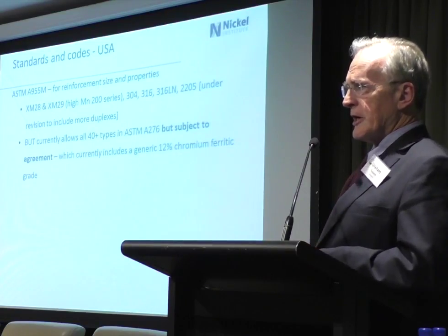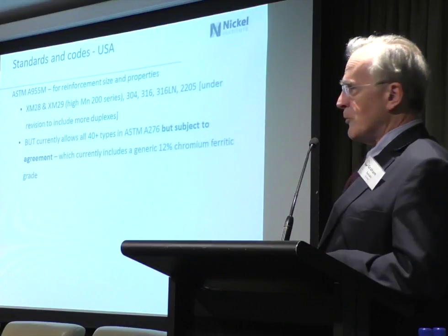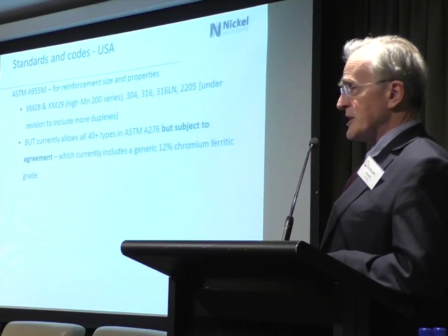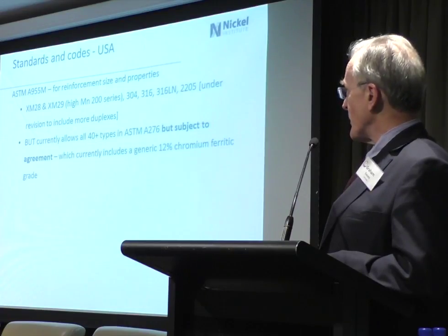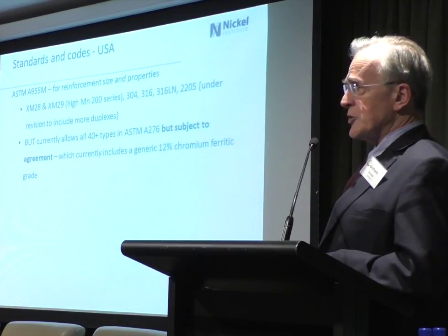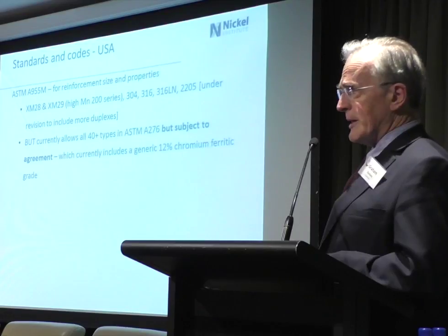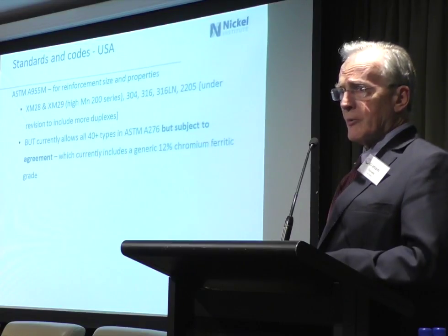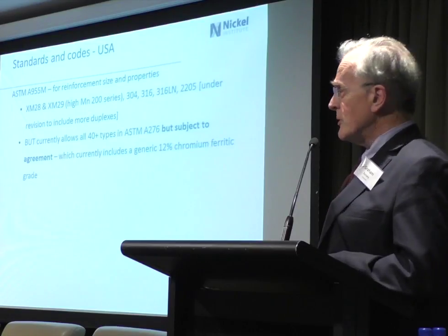Clearly, they're not going to get in there, because there are some fairly stringent corrosion tests involved that they just wouldn't pass. There is another issue: if you try and make deformed bar out of ferritic stainless steels, you may well wind up with cracks, which isn't all that good.